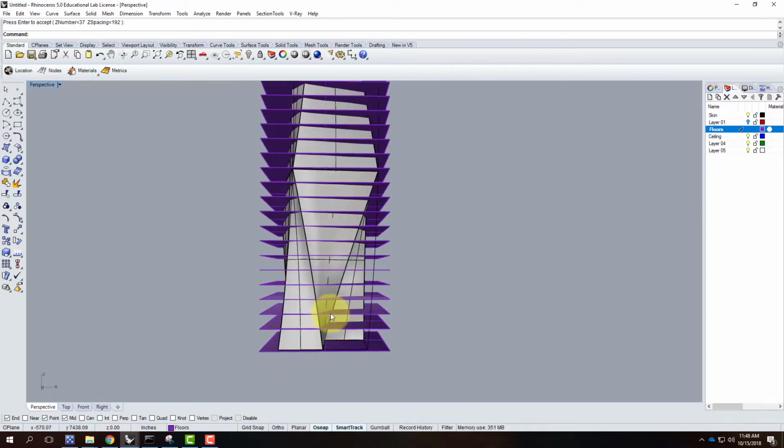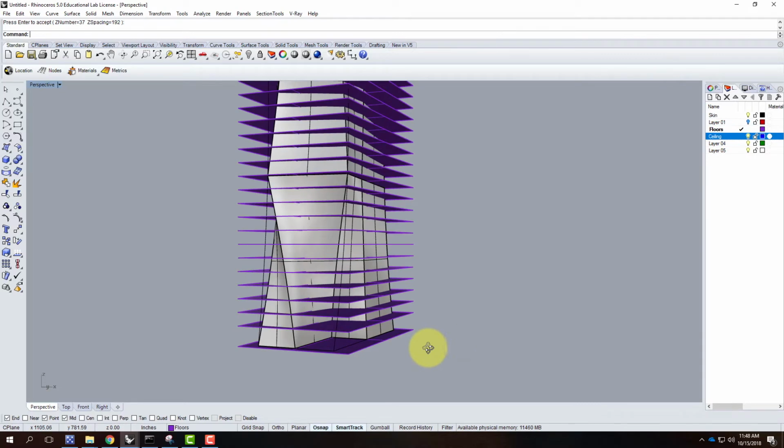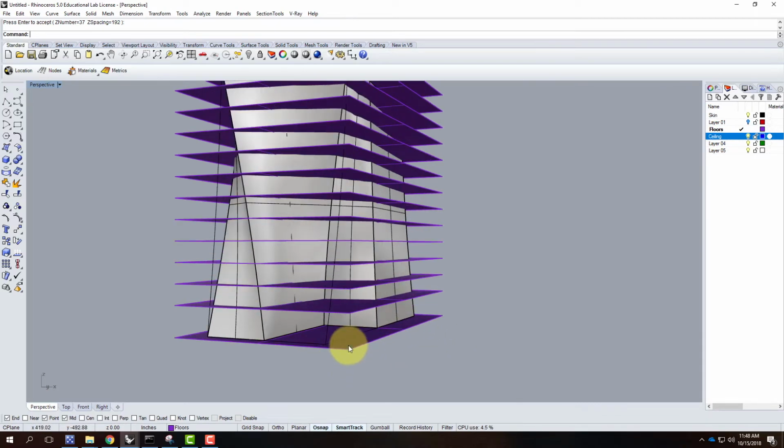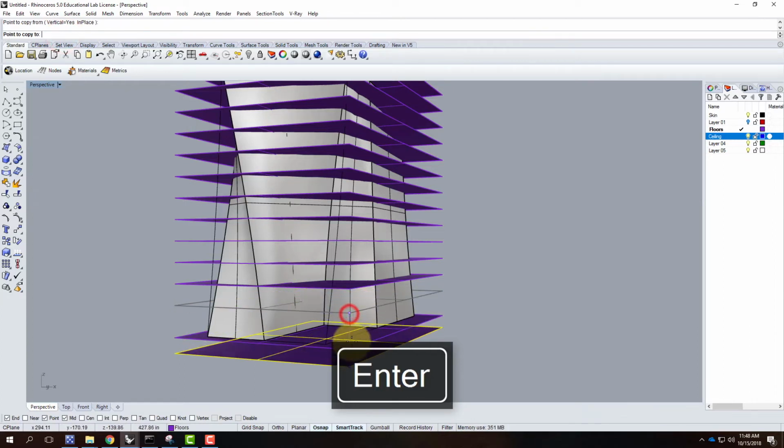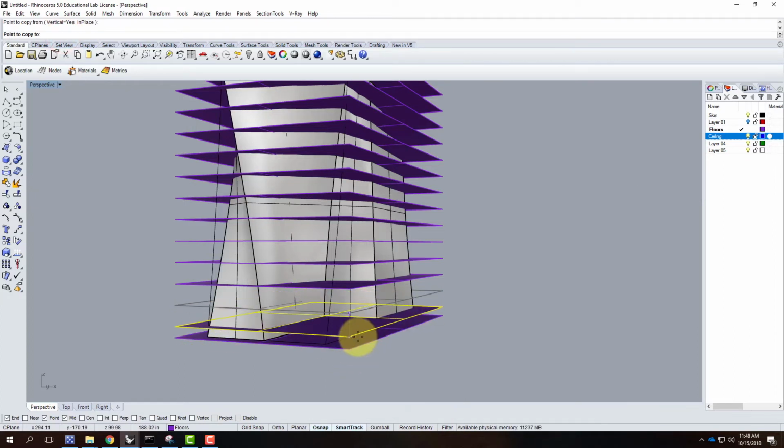So those are my floors. My ceilings are going to have a different material on them, so I want to create a different ceiling plane. So let's take the first one right here, and I'm going to make a copy again, and I'm going to drop it. I'm going to go vertical, but I'm going to go down. And we'll say -4 feet.